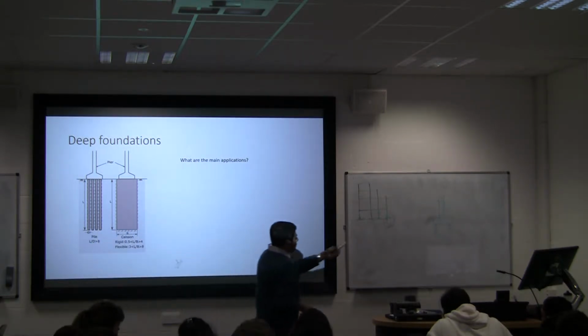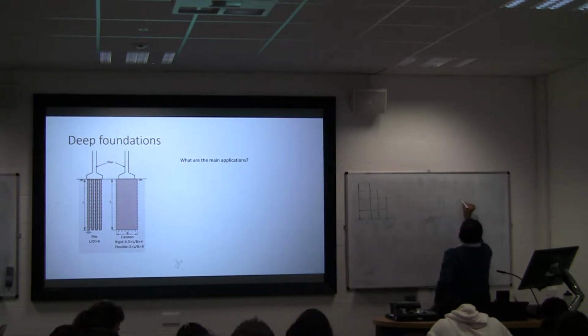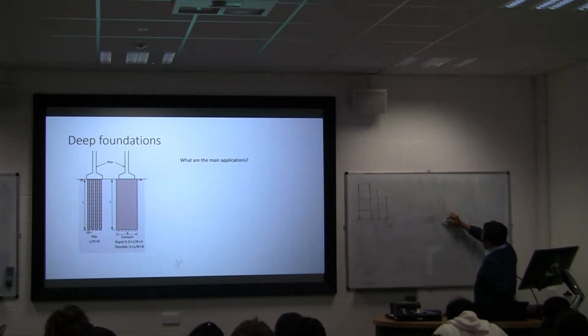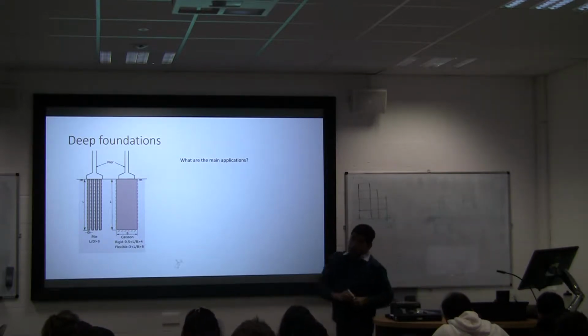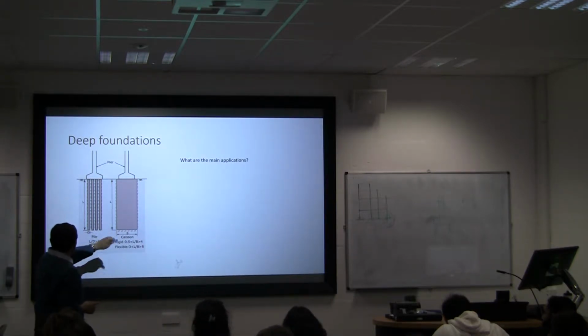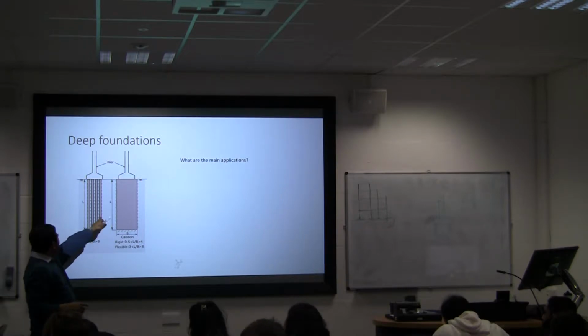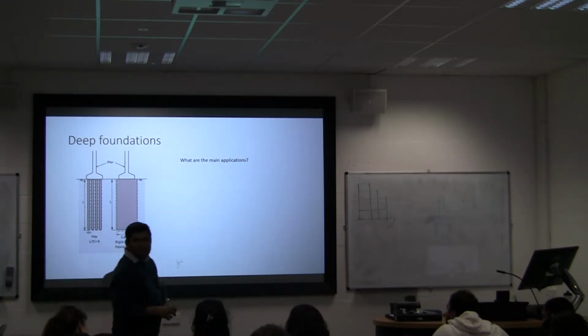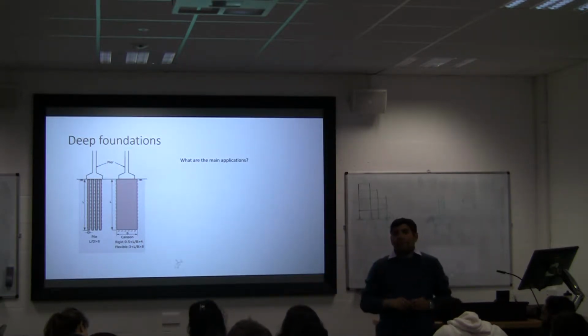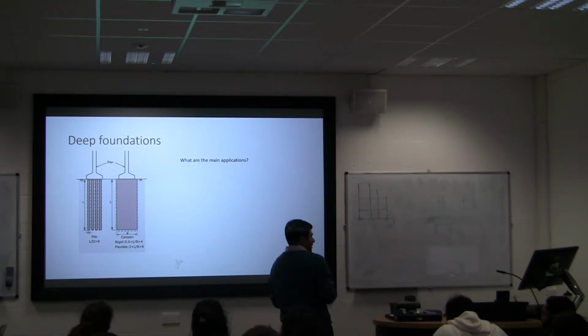So the column reinforcement, say the column looks like this. You have got reinforcements like that. These reinforcements have to come down all the way to the pile cap to have the connection based on what you have assumed in analysis. Okay, so that's an example of this. And can you give me an example of this case? A bridge pier, yeah. A large bridge, you know.